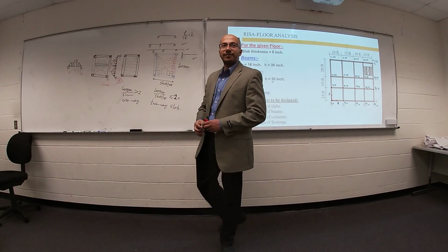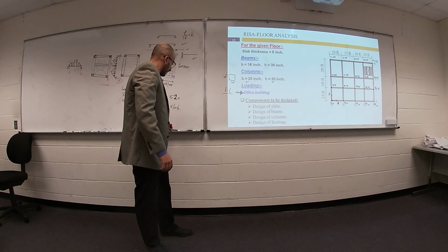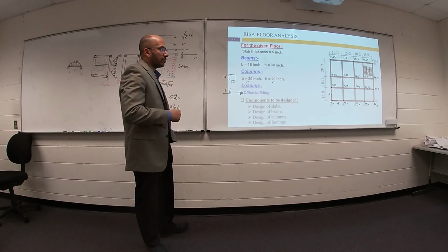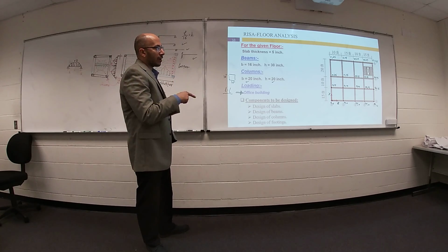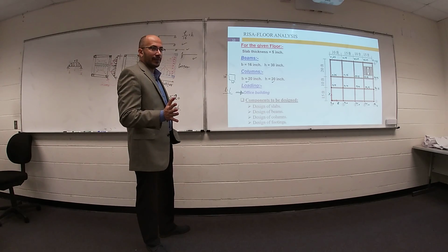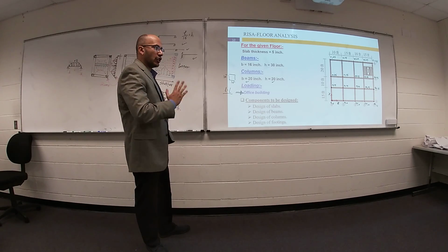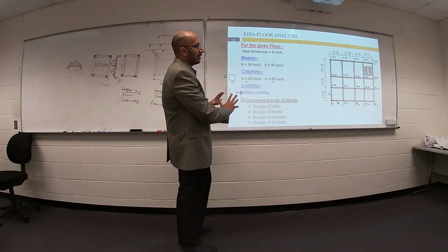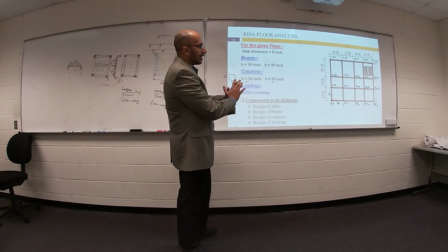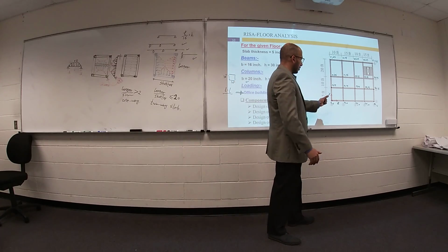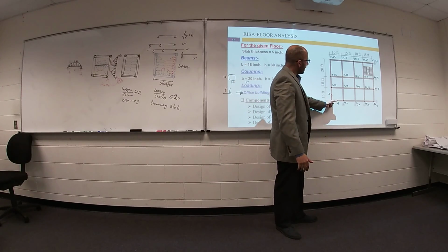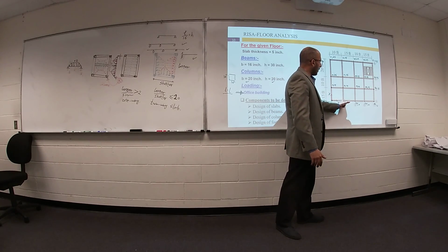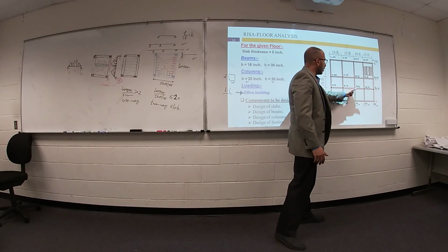What do you think? Lot. Yeah, we have many. If you have a very large area, we have many, but we have another option. You can move your drawing from AutoCAD to RISA. If you have your drawing in AutoCAD, you can move it directly. But we need to start first with the basics: how to use RISA to define, then the advanced option. Anyway, so here is your origin. We have Z, we have X axis, so you can define what are the coordinates of each joint.